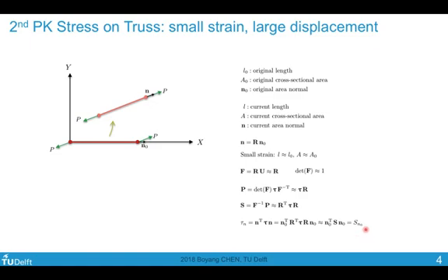So what does it mean? Let's say I have my true stress along the normal direction. If I multiply tau, my Cauchy stress, with the normal n, now I consider the pullback of P as applying the inverse of F on the actual force P times n. P is the magnitude, n is the normal. So I get my P0 N0. This is the pullback force that we talked about last week. And this is roughly equal to R transpose P, because F inverse is R inverse, which is R transpose. Now, P is a scalar, so I can bring it forward. R transpose times n gives me N0. So you can see that on the left side, P0 is approximately the same as P. What it means is that I'm simply rotating this P onto the N0 axis, and this is what the pullback is doing.